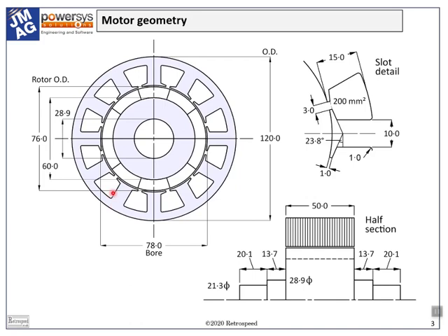The objective is to design the winding and then calculate the electrical parameters of the equivalent circuit so that we can estimate the performance. We can divide the winding design into two parts. The first part is the layout of coils. We have 12 slots and we're going to use 12 coils, so we will have 2 coil sides per slot. That is called a two-layer winding or double layer winding.